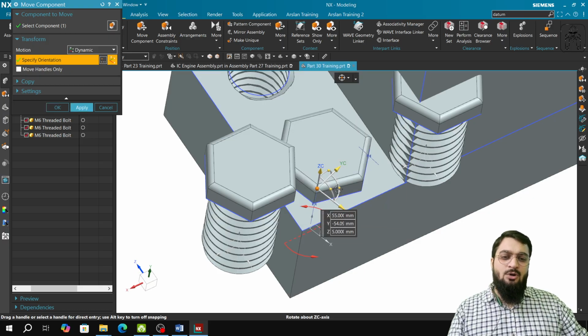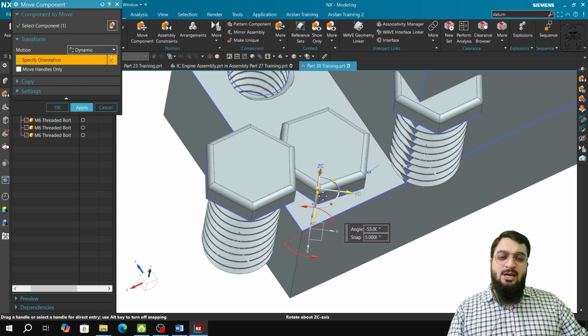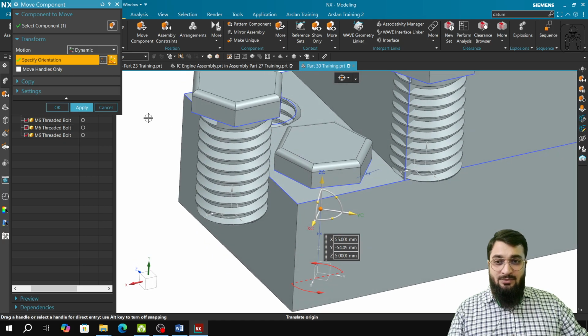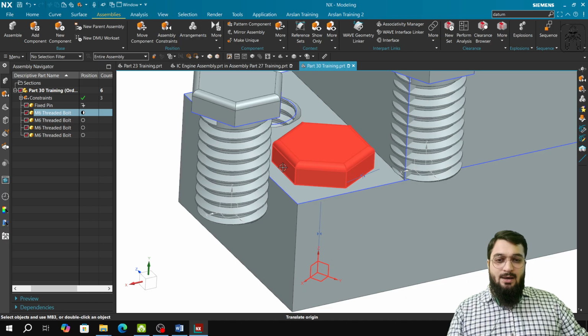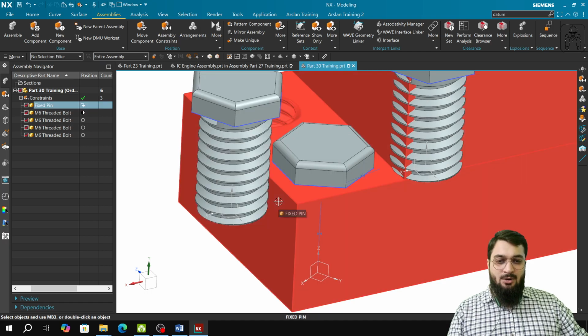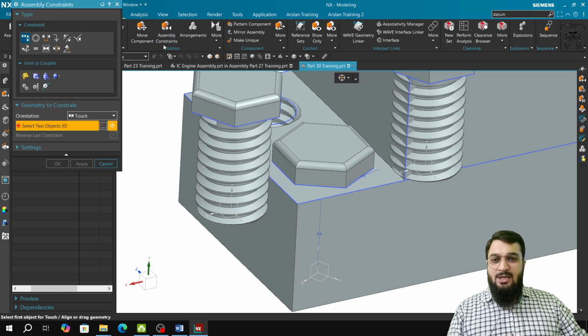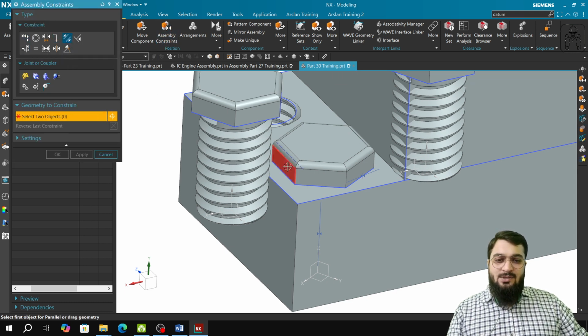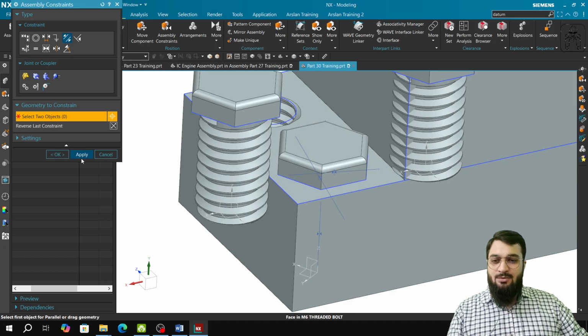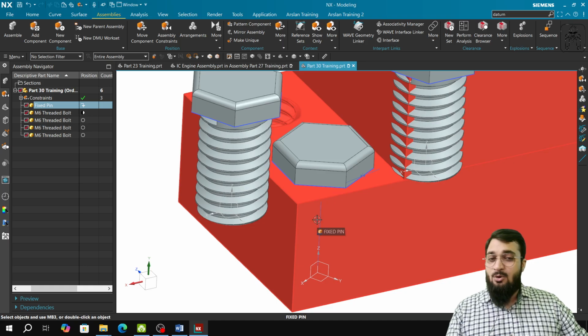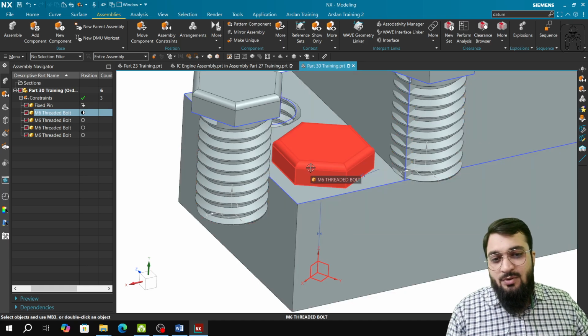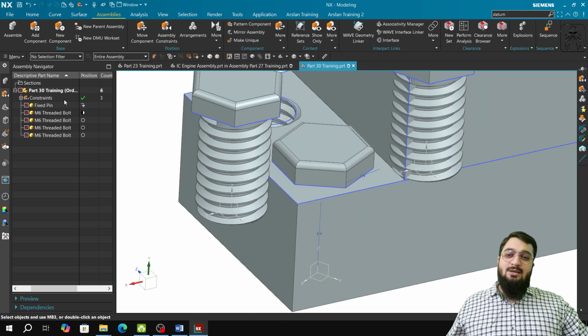Now I want this body, after getting fully tightened, the fixed part in the fixed pin, I want it to be like this face is already parallel to this. Let us make this face parallel to this face. So I will go to assembly constraints, take the parallel, select this and select this. It will get parallel. As of now, we are not studying the parallel constraint, so we'll let it be like that.